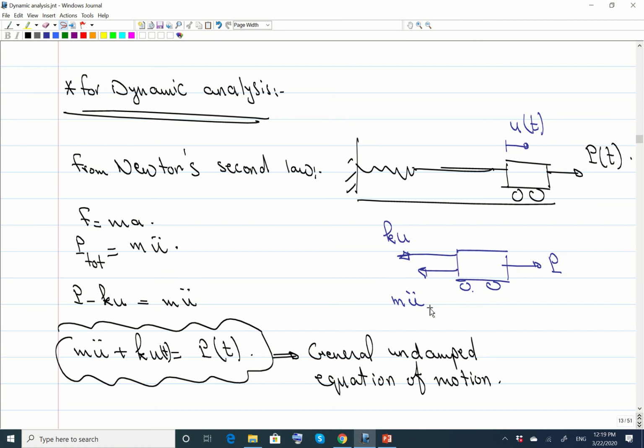You're still gonna move the car until you reach 40 miles an hour, but the rate or the acceleration is so slow. The cup of coffee will not get spilled. It's not gonna move backward. That means that the force that is applied backward on this cup of coffee depends on the acceleration, okay? The acceleration, the rate of change of velocity, as the acceleration increases, the backward force that is applied on this cup of coffee increases. This force that is applied on this cup of coffee is called the inertia force.